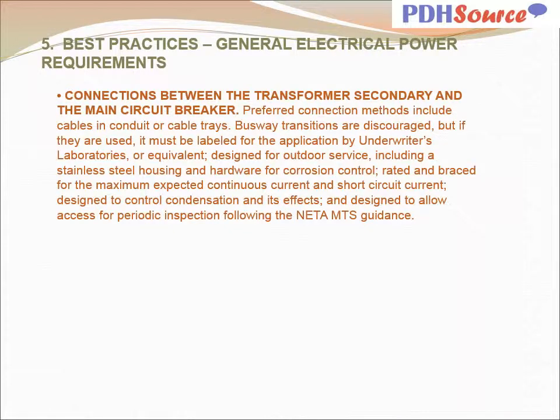Preferred connection methods include cables in conduit or cable trays. Busway transitions are discouraged, but if they are used, they must be labeled for the application by Underwriters Laboratories or equivalent. Designed for outdoor service, including a stainless steel housing and hardware for corrosion controls. Rated and braced for the maximum expected continuous current and short circuit current. Designed to control condensation and its effects, and designed to allow access for periodic inspection following the NETA MTS guidance.